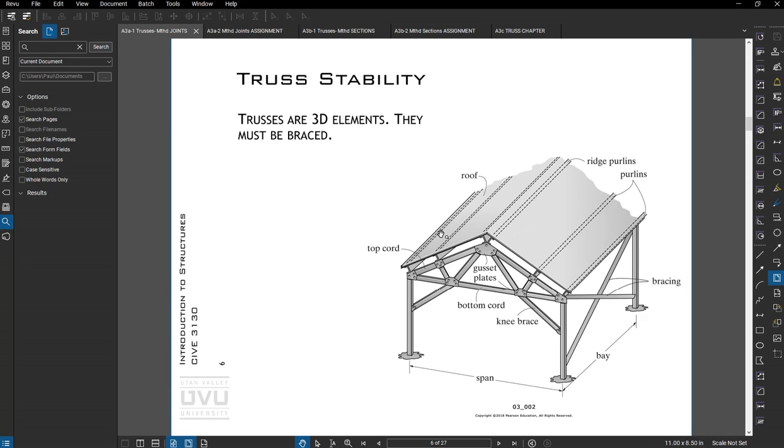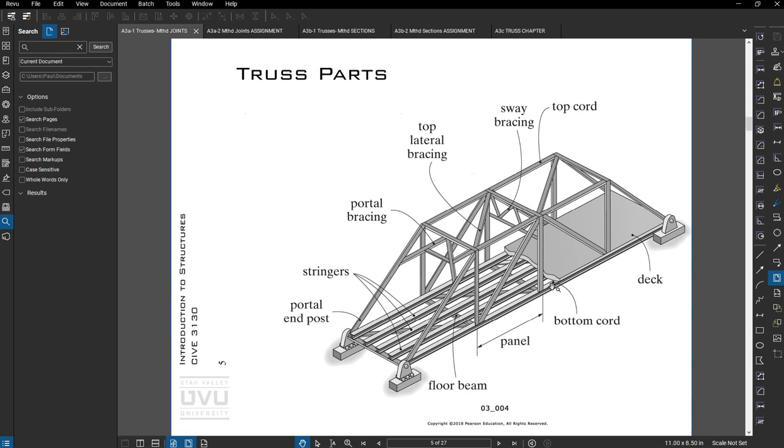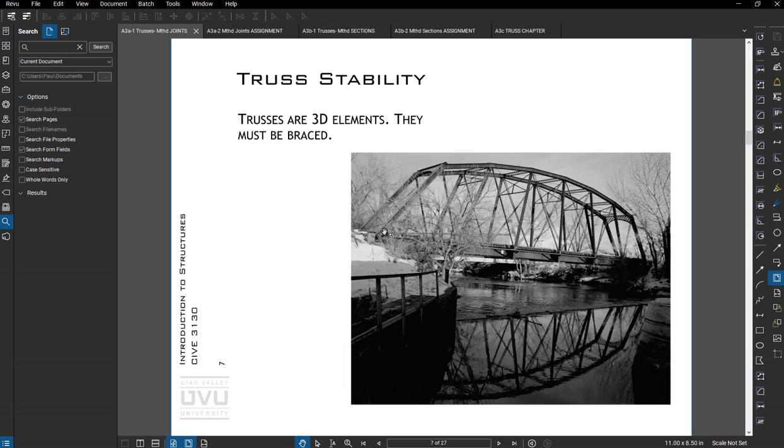In a rail bridge, something like this is our top chord of the truss, bottom chord, diagonals. This little lattice structure with the two columns here, that actually is a portal frame or a moment frame. So a train can drive through here, but this frame is stiff enough that it keeps the truss from tipping over. And it receives load from those little thin bars or rods and those little lattice truss members.